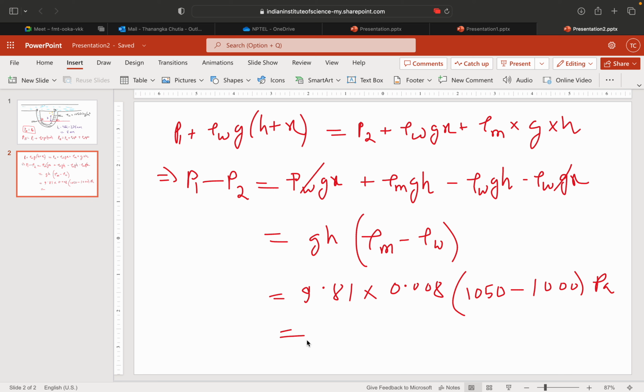So 9.81 into 0.008 into (1050 minus 1000) will give you the answer. The pressure difference is 3.924 Pascal.